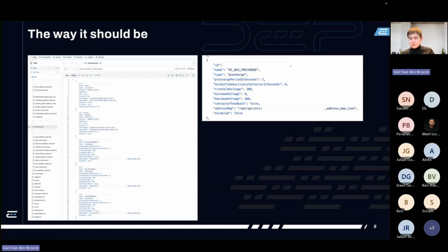In this approach, you just copy paste this block one by one. You adapt the values, and you basically load it into a controller. You don't even have to restart it. You don't have to compile the code again and restart from scratch. No, you reload it. The controller OS will detect, oh, a change in my config settings happened, and it will refresh its device states. So you can do a soft restart instead of going through a full compile cycle, which can also take many minutes. And when you're testing and troubleshooting something in practice, that's annoying.